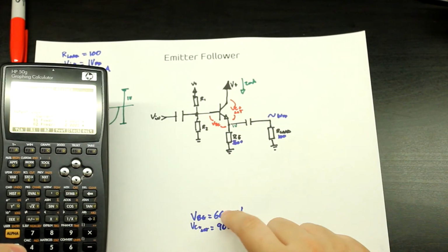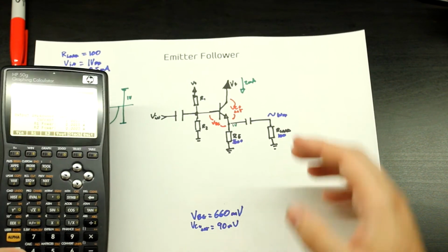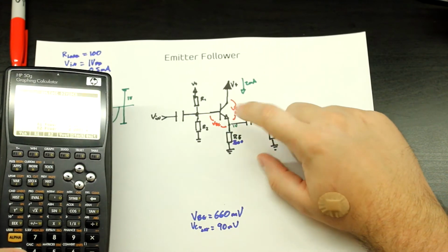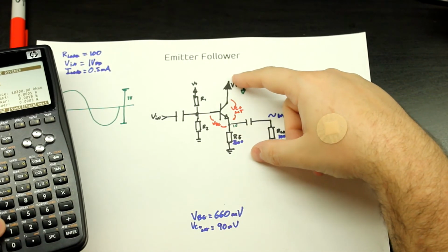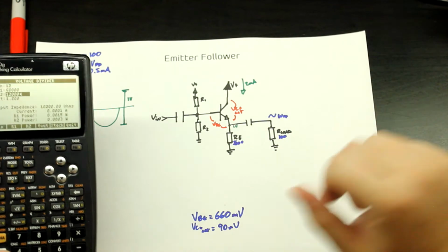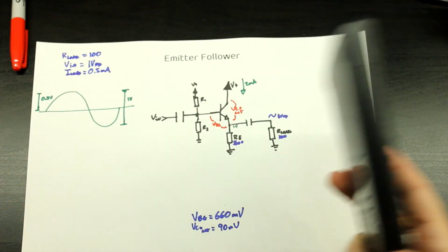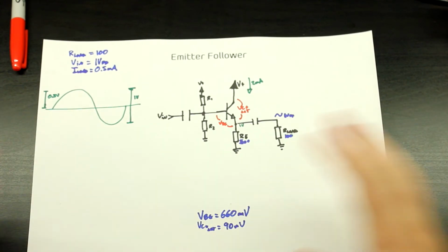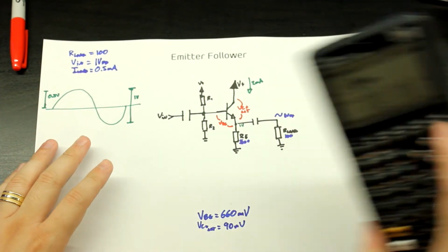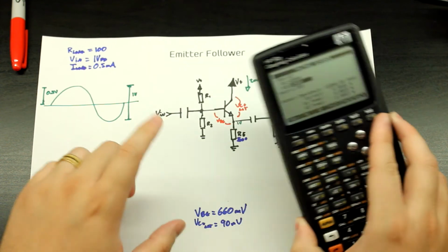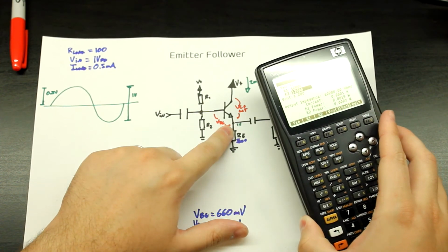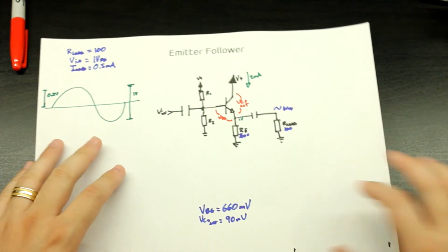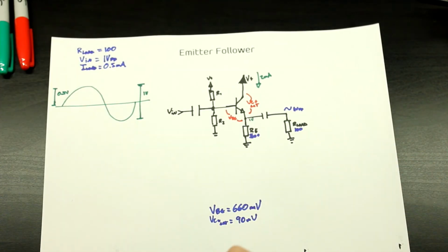In the case where it is 1.6, 1.7, it means that we will have around 100 millivolts more in this node, so it's going to pass 2.2 milliamps, but hey, that's all just margin. It's the real world. We're not doing any theoretical stuff here, so that's good enough. So we'll have 1.8 volts here at the base, around 1.2 volts here. So it all works out in the end. So let's just write this out.